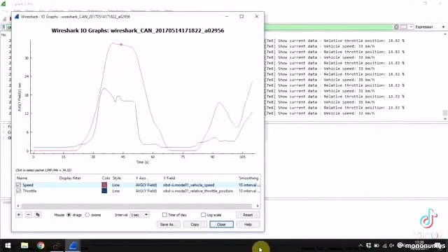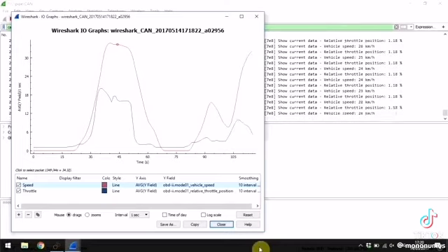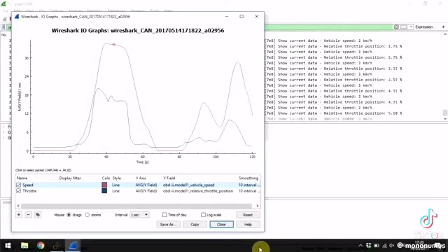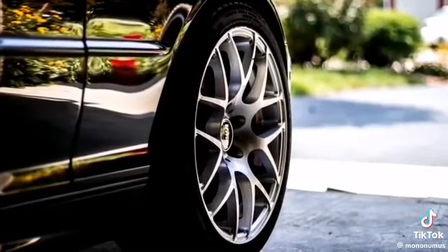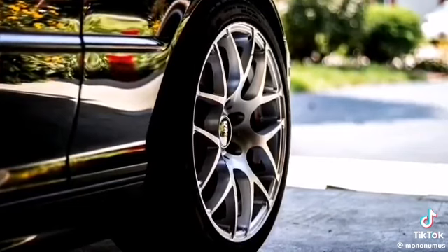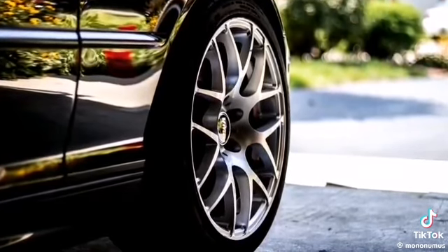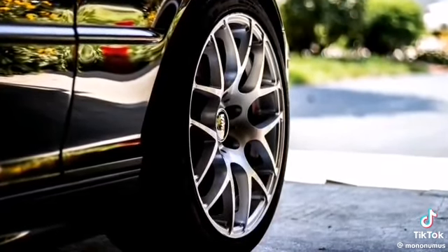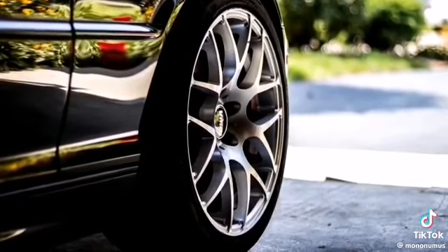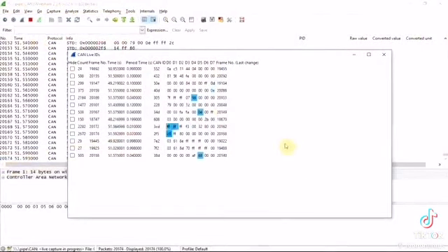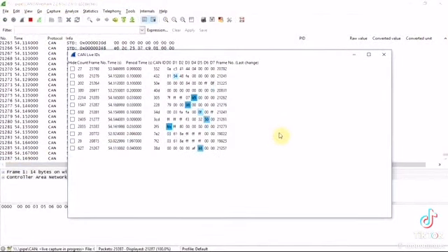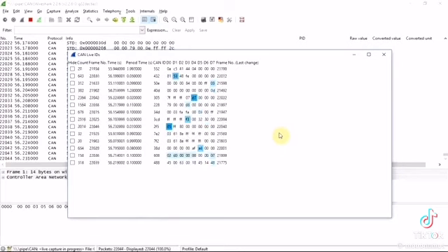A lot of this data is also available outside the OBD2 protocol, but these CAN messages are typically proprietary. This means that you would need to decode them via a database of conversion rules/parameters, which is not always available. As such, for example, car hobbyists accessing such data would require reverse engineering, CAN sniffing, or hacking. In other words, the OBD2 standard is often the most convenient way to access basic data parameters from your vehicle.